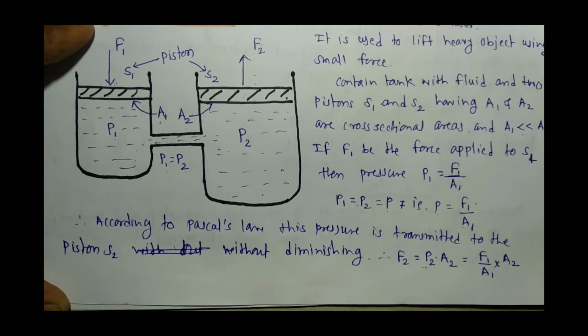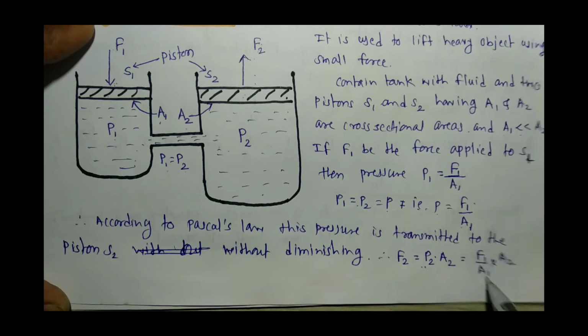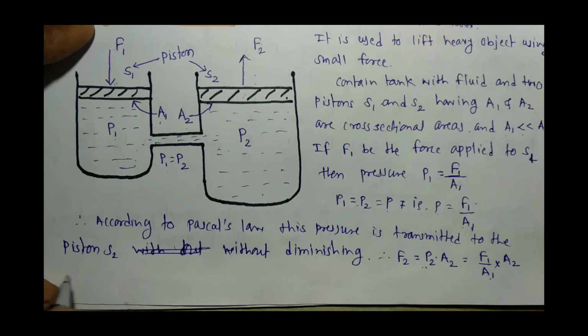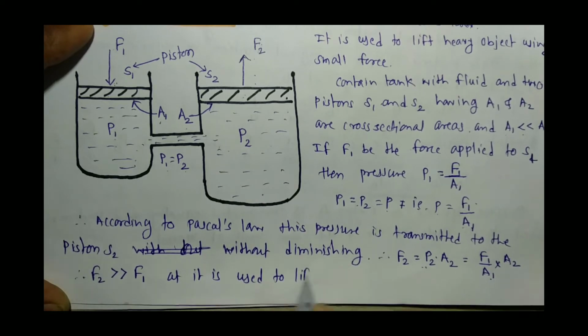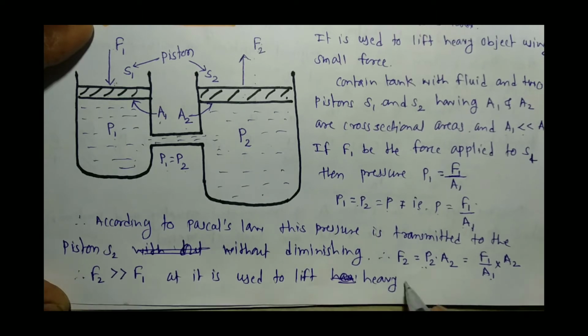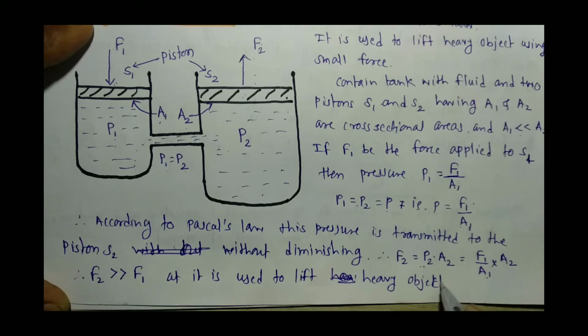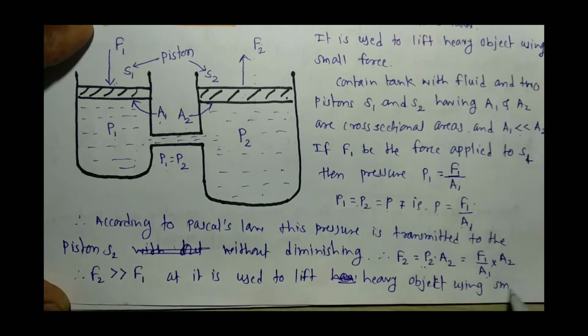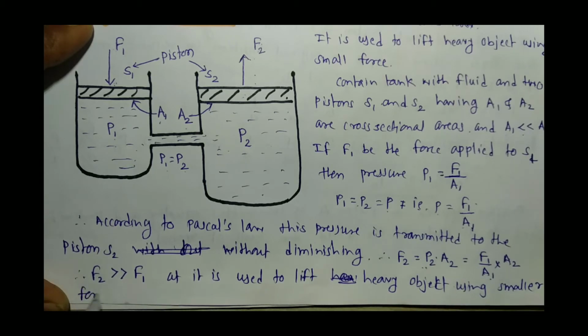As A2 is much greater than A1, F2 is much greater than F1, and it is used to lift a heavy object using a smaller force, that is F1. This is your principle.